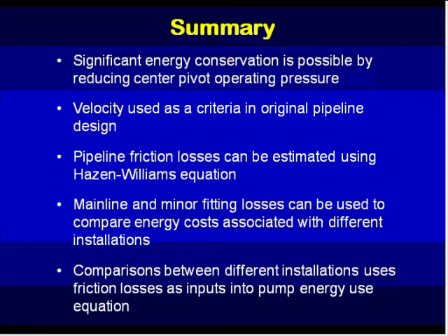On the pivot pipeline, each place where a sprinkler comes out, one could attach a gauge to it. Now, these kinds of things tend to be either screw them in place and have several of them on hand and screw them in different places and go along after the system is in operation and record them, or go along and place them in the outlet as best you can.